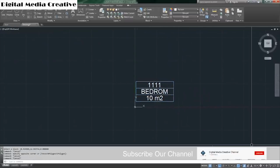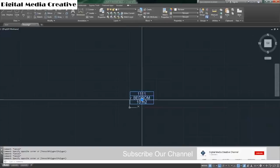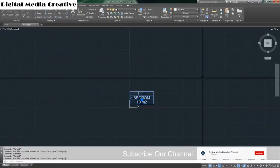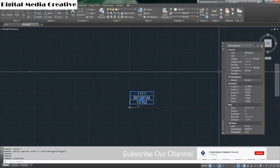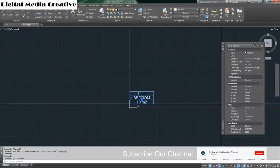So whenever you are making a block, it's easy to make it in 1:1. Whenever you have a different scale, you can easily change it in the properties. When you select it, in the properties you can see scale X, Y, Z, everything 1.